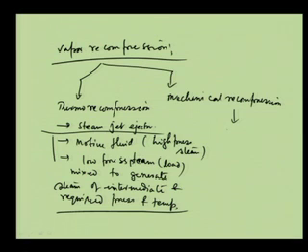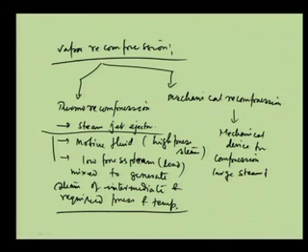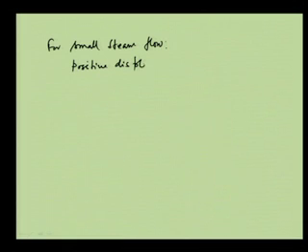But in case of mechanical recompression, what is being done? A mechanical device is used for compression. For large steam flow, a centrifugal compressor is used, and for small steam flow, a positive displacement compressor is used.